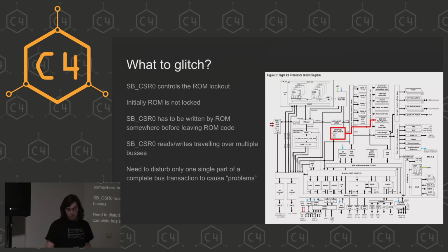Also, we still need to run code. It's not enough to just glitch away that register write. Our code that runs after the ROM still needs to be able to read out that ROM and dump this to the serial port so that we can get a dump of the ROM.